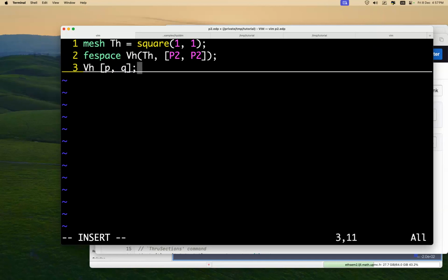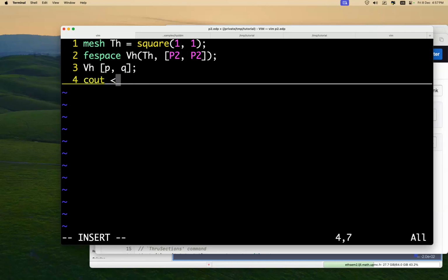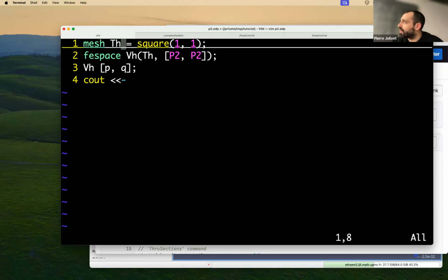We just have to give them a value to have a vector when we plot. Yes, but you have to be careful with the plotting, because the plotting is only linear. So what it does is basically refine the mesh and then interpolate from the P2 to a P1.